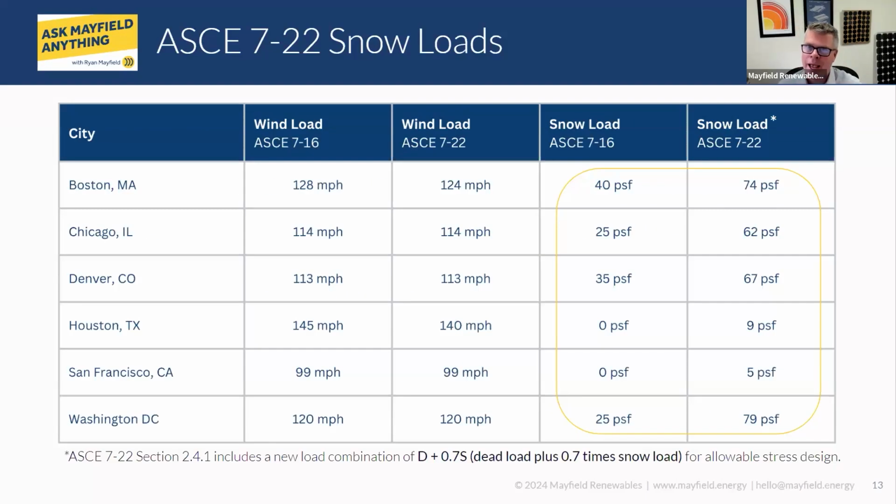I guess the question that I have is, how do you properly apply it then? So if you have a PV system you're going to install on this roof now, we just did that math, the 40 PSF, really more of the apples to apples, as you were saying, is more of a 52 pound. So we're saying that's what the loading for the snow load is now. And so now adding solar onto that, we may have a situation where structurally the building may not even pass the updated snow load. Am I understanding that properly?